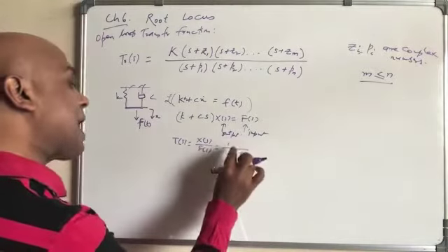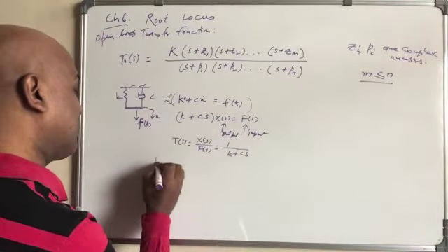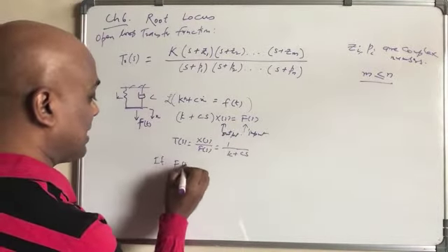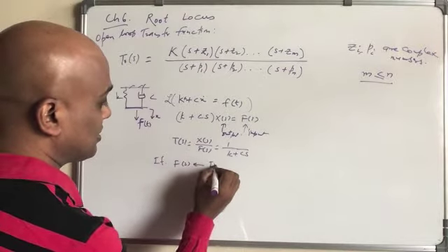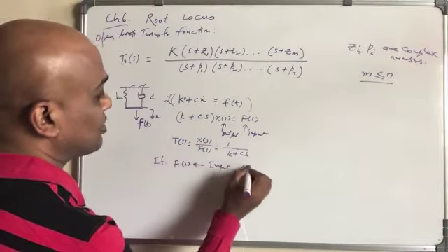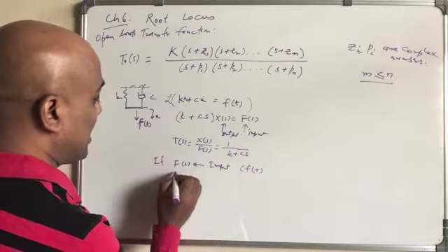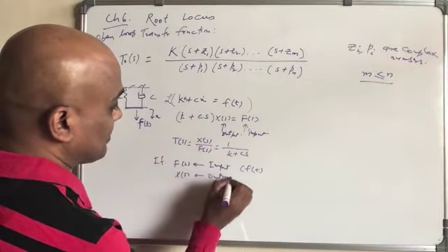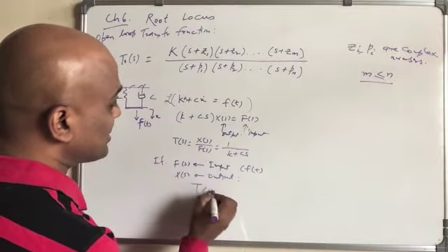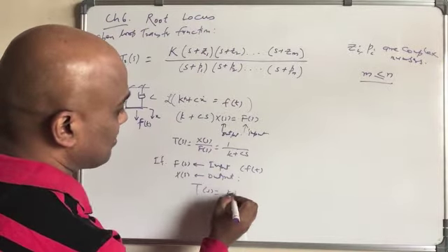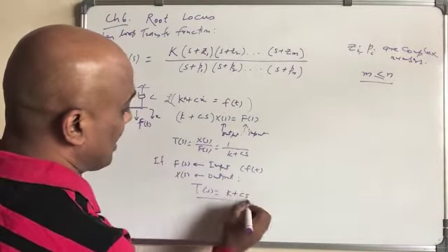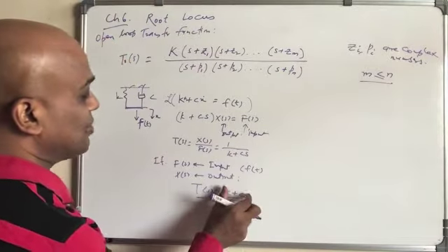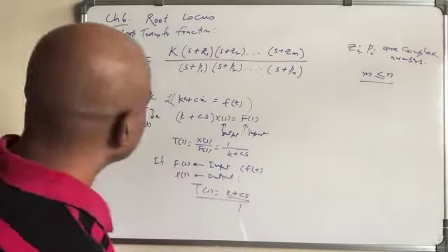The numerator can have the higher order only if x(s) is the input and F(s) is the output, in which case the transfer function is K plus Cs.